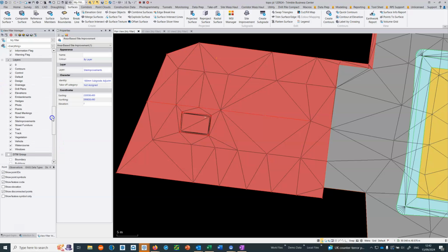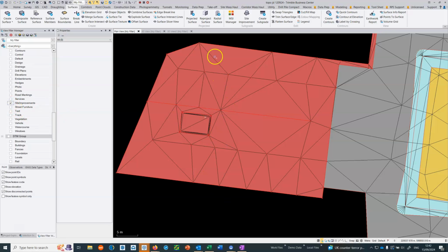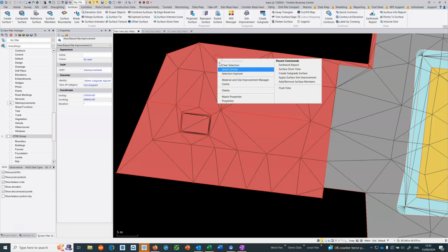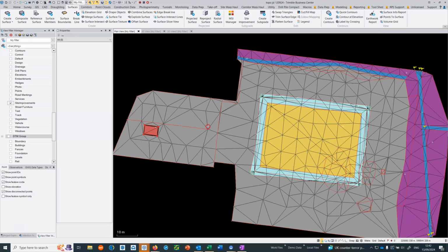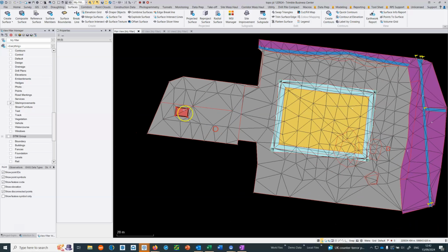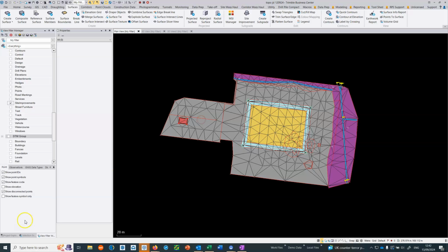We'll keep the surfaces on. So we turn off all our layers and we see our site improvements. Then we can see these seed points. If I want to get rid of that, I just select it, hit delete, and that site improvement will disappear. So these seed points are very important in this particular workflow.